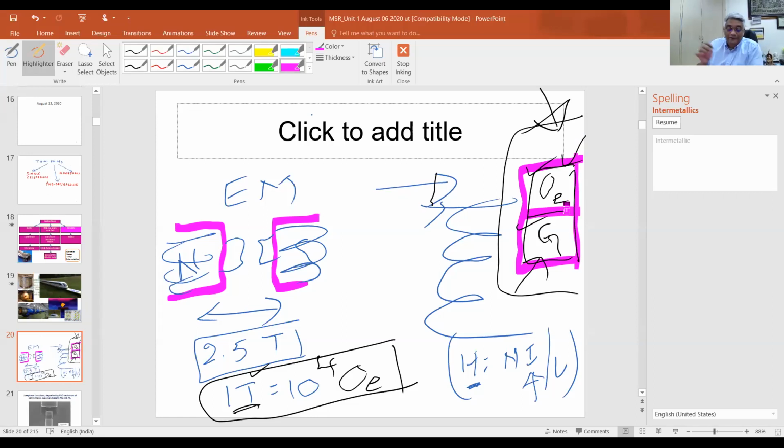Okay. Anyway, so now the point here is to construct an electromagnet that you see in the lab. The lab electromagnets that are used to do a typical Hall effect measurement are not more than 2,000 oersteds. The maximum you can go is 2.5 Tesla. To get 2.5 Tesla, 2.5 into 10 raised to 4 oersteds of magnetic field,